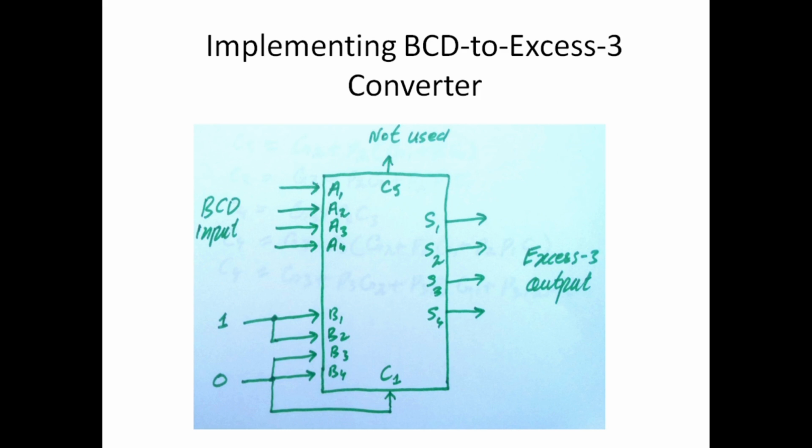Also, there may be more inputs in a logic circuit than is feasible to handle using the K-map method. For example, using the BCD to XS3 converter, we have already seen that there are 9 inputs and 5 outputs. Using the K-map method, we would have 2 raised to power 9 rows in the truth table, and we would require a 9 variable map. Imagine that even a 6 variable map is too cumbersome to design and simplify.